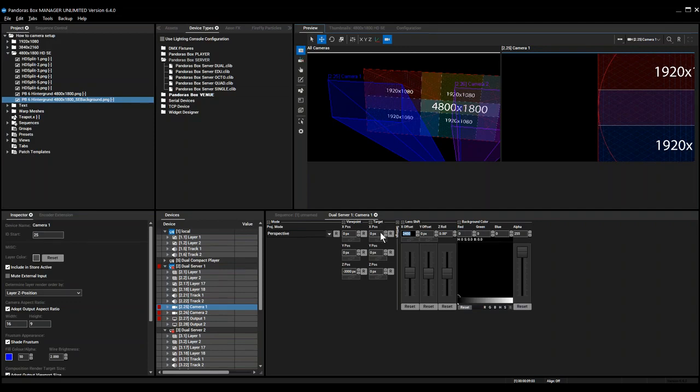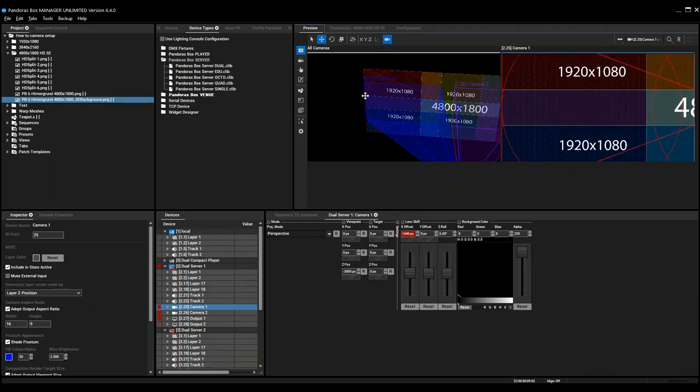So that means I put it in completely again, just for you, 4800 divided by 2 minus 1920, because that's the resolution of my output, divided by 2, because it's only half of it, right? So I put this calculation in here, press enter, and it directly hits the X limits exactly, right?